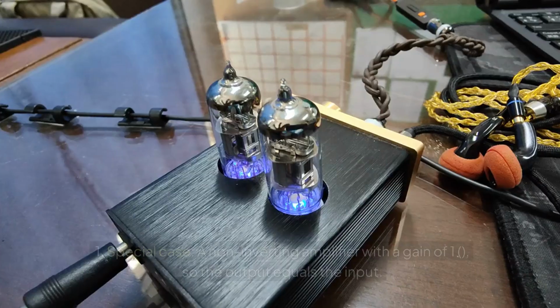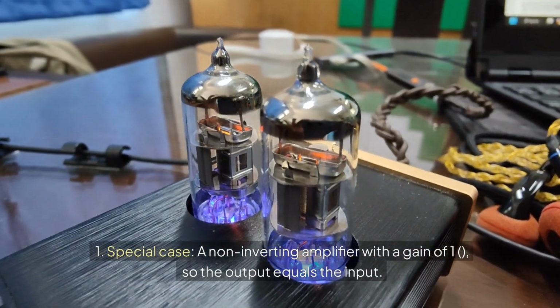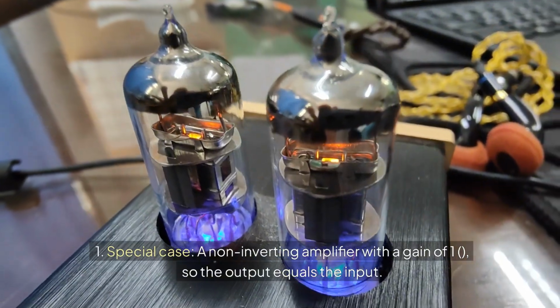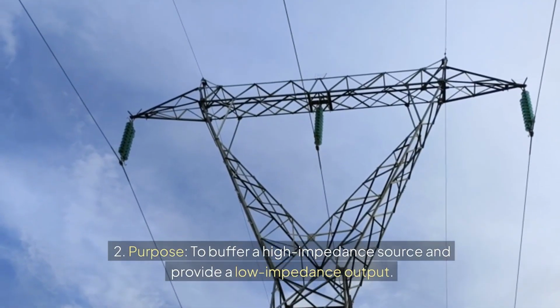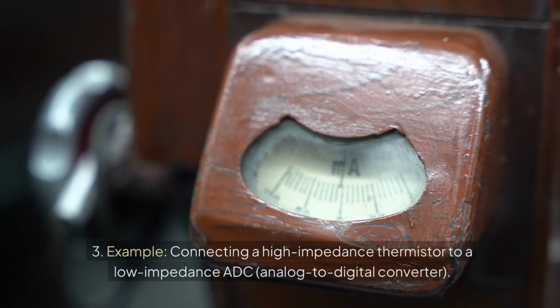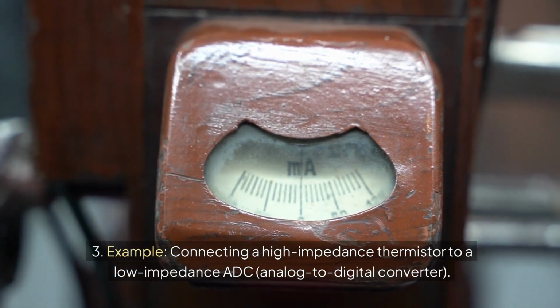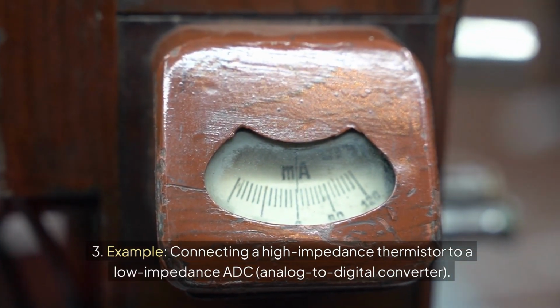Voltage follower. 1. Special case: a non-inverting amplifier with a gain of 1, so the output equals the input. 2. Purpose: to buffer a high impedance source and provide a low impedance output. 3. Example: connecting a high impedance thermistor to a low impedance ADC, analog to digital converter.